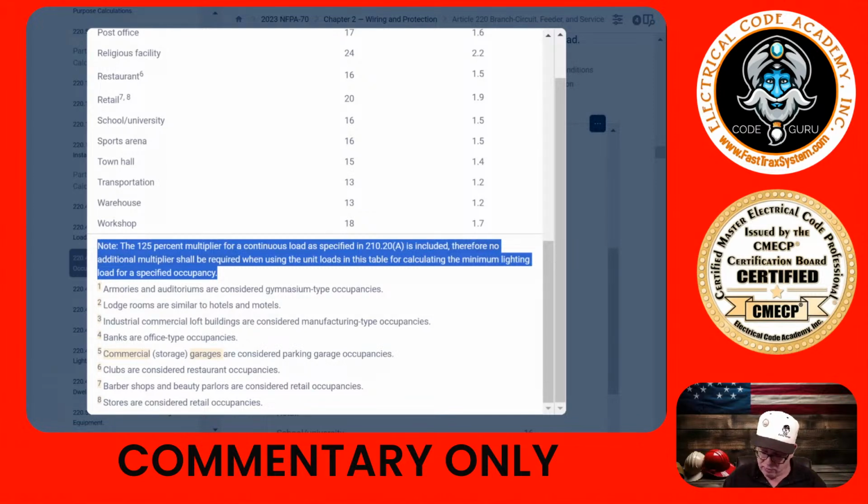Let's say we have a 50,000 square foot office building. That's its dimensions. So it would be simply 50,000 times 1.3, and that is 65,000 VA. Let's double check: 50,000 times 1.3 is 65,000.